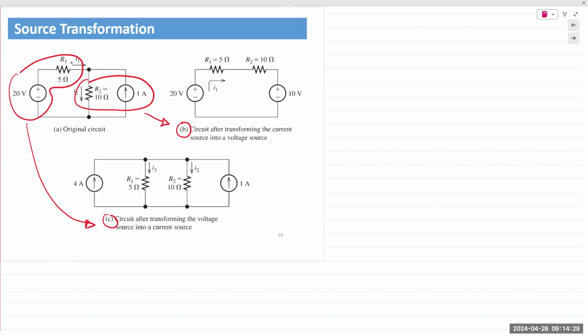Okay, now you simply have two voltage sources in a circuit, or you have two current sources in the circuit. You can simply apply Ohm's law and solve the entire circuit. Apply KCL, KVL, and solve it. So instead of performing multiple steps of node voltage analysis and writing out equations, or mesh current analysis or superposition, it is now a 2 or 3 step answer. Okay, so let's see how this will work.